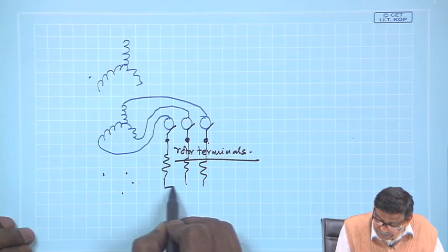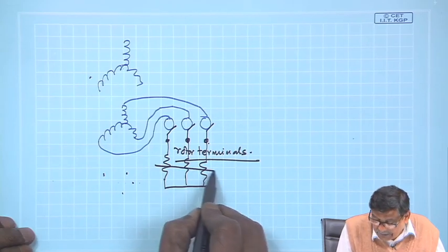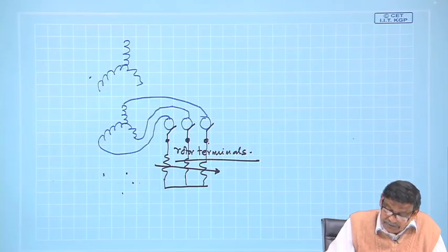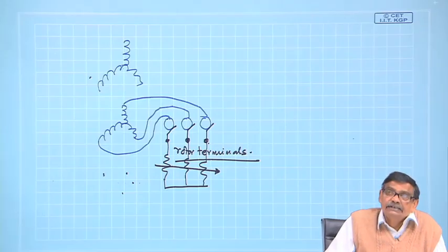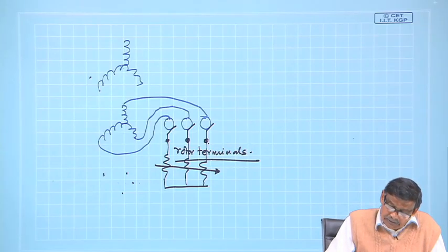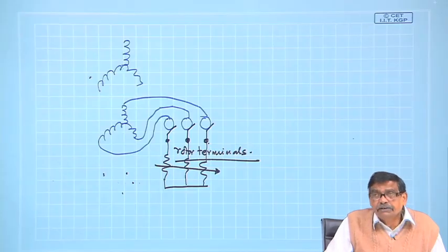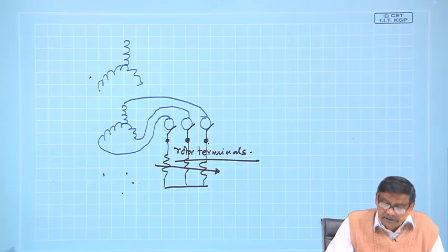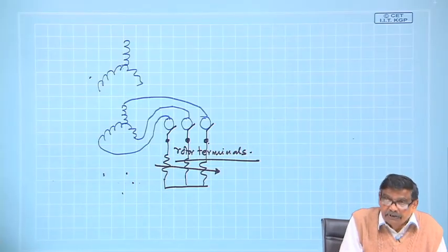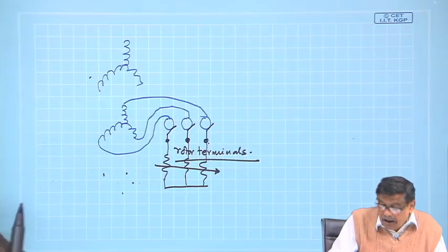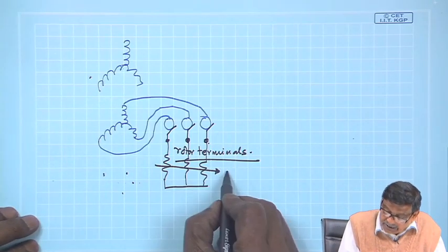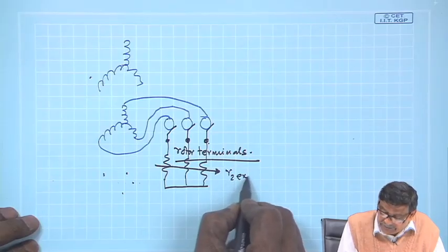This is one of the very nice points about the slip ring induction motor: you can vary the starting torque, and you can even make the T max, which the motor is capable of developing at some slip, appear at s equal to 1 by appropriately connecting external resistance to these terminals.